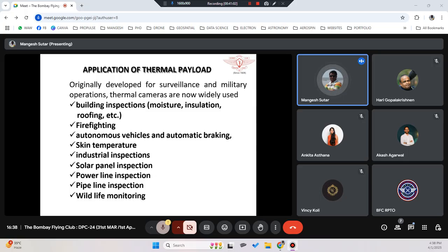So we checked randomly. The water irrigation department checked those locations, and they tried to open up those pipes and check why these kinds of image differences were there when we were capturing the thermal images. We came to know that there was huge corrosion happening at those particular locations.